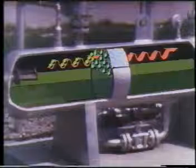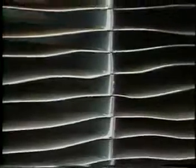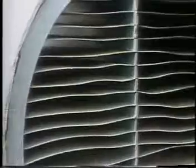The effectiveness of wire mesh depends largely on whether or not the gas is traveling at the proper velocity. If the velocity is too high, the liquids knocked out will be re-entrained. If the velocity is too low, the vapor will just drift through the mesh element without the droplets impinging and coalescing. Vane-type mist eliminators force the gas flow to become laminar between corrugated parallel plates.